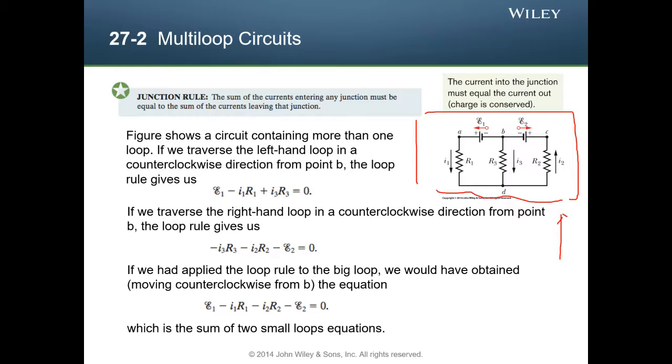So we'll assume 2 loop currents for these 2 loops, going counterclockwise. So for this resistor, we will have voltage drop R1 I1, and for this voltage source, it is also a voltage drop, so it is positive. And for R3, I1 is going clockwise.